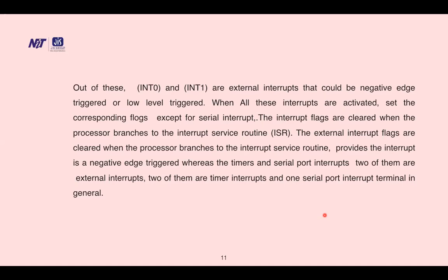The external interrupt flags are cleared when the processor branches to the ISR, provided the interrupt is negative edge triggered. Two of them are external interrupts, two of them are timer interrupts, and one is the serial port interrupt.